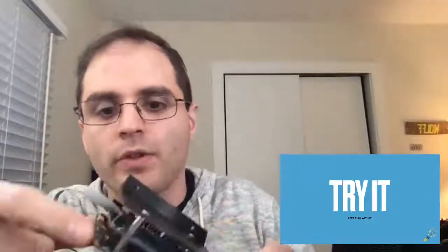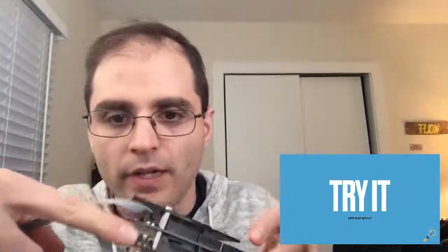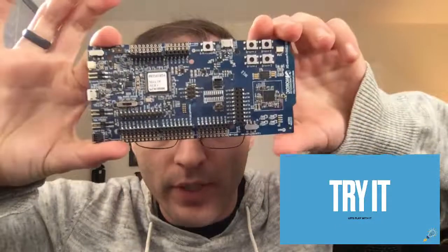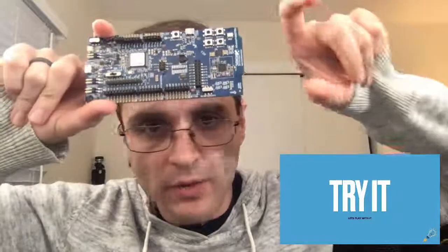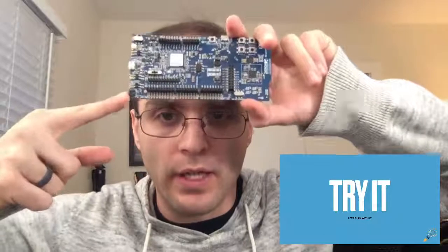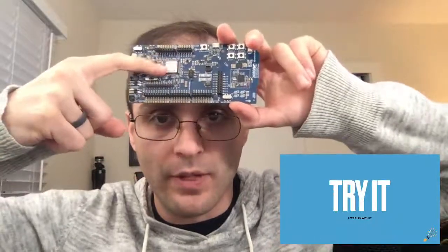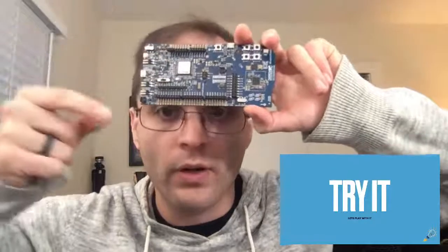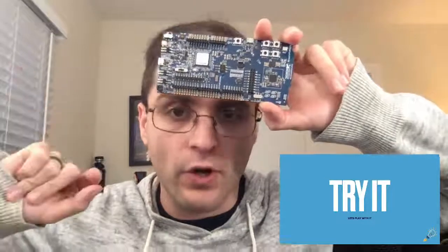It's very common. The Nordic boards have the external debug connector on this corner. Sorry, I don't have a better one here. I think I have another one here. So Nordic dev boards, they all pretty much look the same. Sometimes they extend out further if you have more functionality, more hardware. But this is the external debug connector. So this allows this processor, loaded with Segger's firmware, to program external targets.